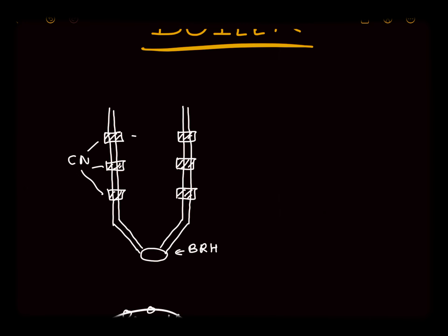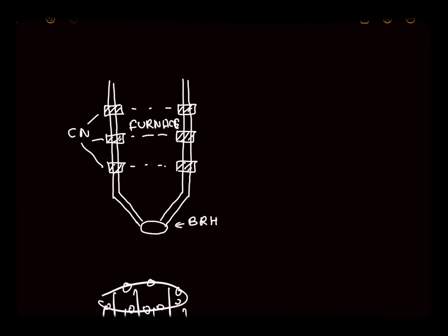So this whole area is called furnace, because the powder form of the coal is sprayed out or thrown out from this coal nozzle, and then it burns, it releases radiation and convection current, and by that heat the water inside the water tube gets heated. So these are water walls or riser tubes.